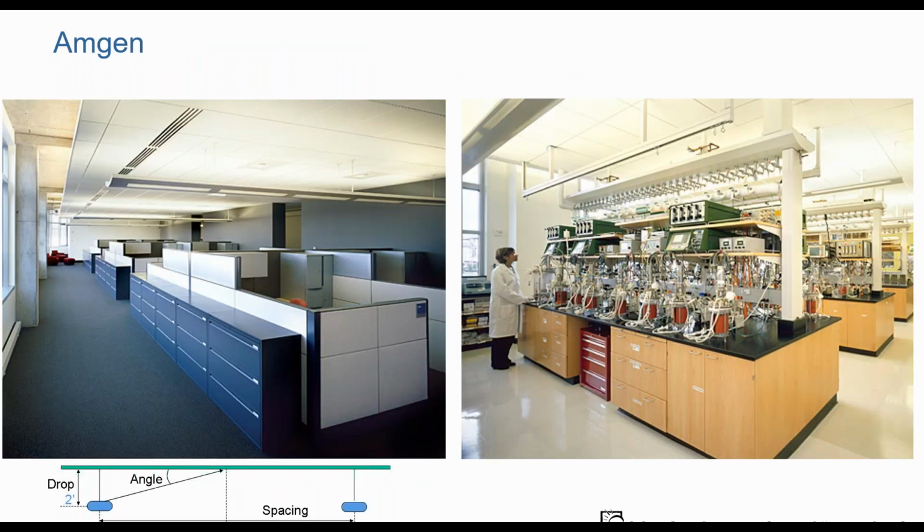So they allowed us to do things like having lighting systems with very wide spacings so that they would match the expressed architectural modules. They would also allow us to have daylight responsive systems in there. Same thing in the labs. We had a relatively new kind of lighting system within the labs where we were using indirect lighting. This has become standard for a lot of labs now. We had a much lower measured light level at the lab surfaces because we had higher perceived brightness from the indirect system than we would with the direct system.